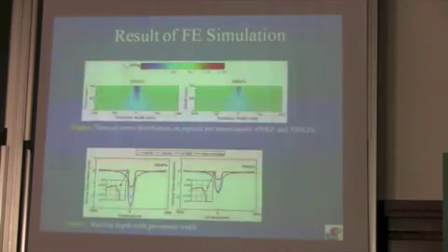Right. So now 2 millimeters is not sufficient to make you experience some discomfort. But when we do this over millions of cycles, you can have rutting, and this is what's causing the rutting. But what is even more interesting is that you see there is a little bulge next to the depression that has been caused, and this is what we observe a lot, and you will see some cracks developing there. So some of these effects can be modeled by classical approaches. But what's important here is you end up with a relatively simple model. You do not have to assume yield functions and plastic potentials and damage functions and their evolution, right?